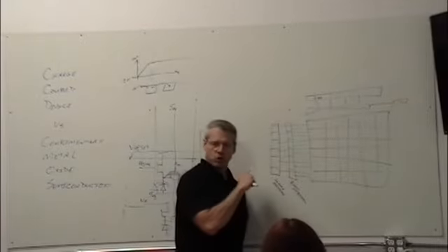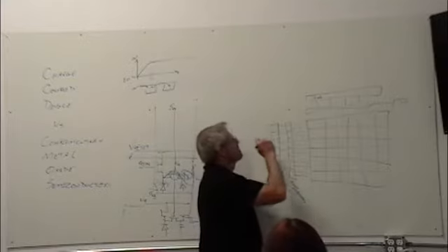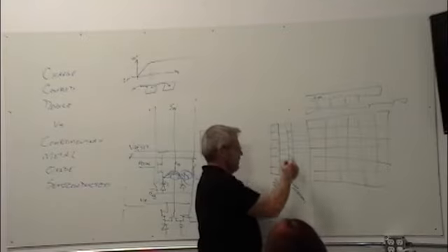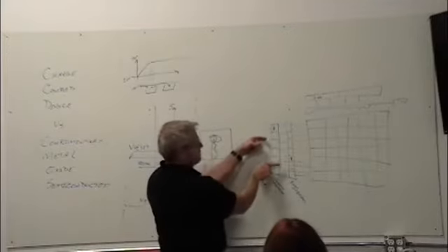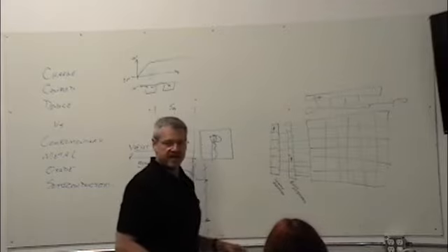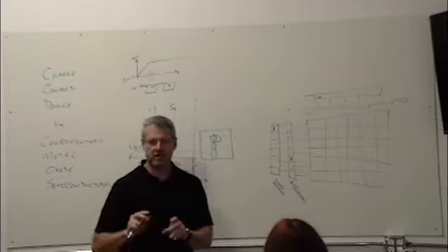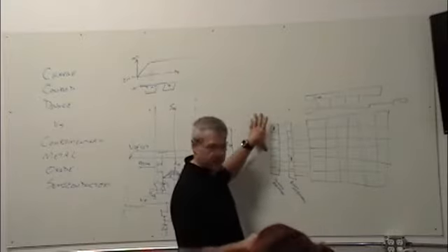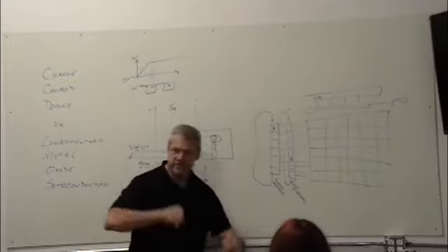This is what's called a rolling readout. You see these, they call it a rolling reset or a rolling readout. Imagine this is a lot more of these than there are. But my reset, I put my 1 here, and my sample, I put my 1 there. And now as it goes along, it resets. Now I can change my integration time, I can change my shutter speed effectively by moving these closer together or further apart. And basically I just have it loop right back around on itself, right? And so it just keeps feeding it through.